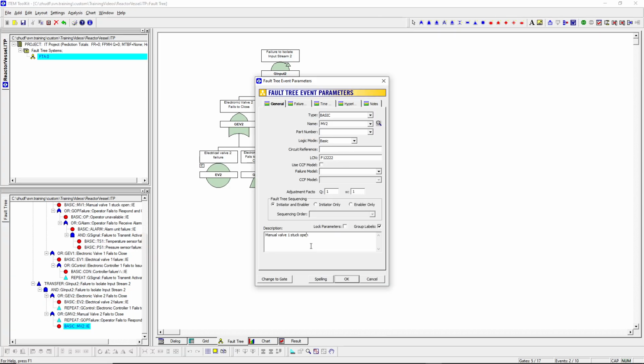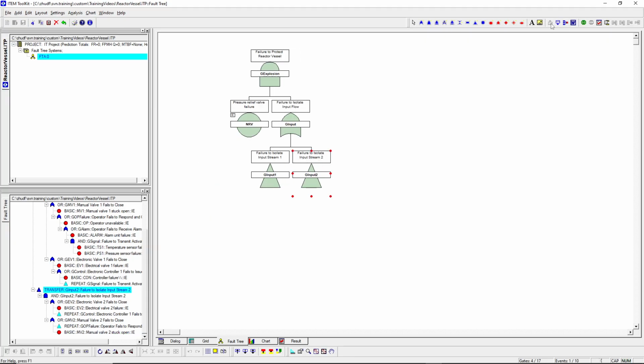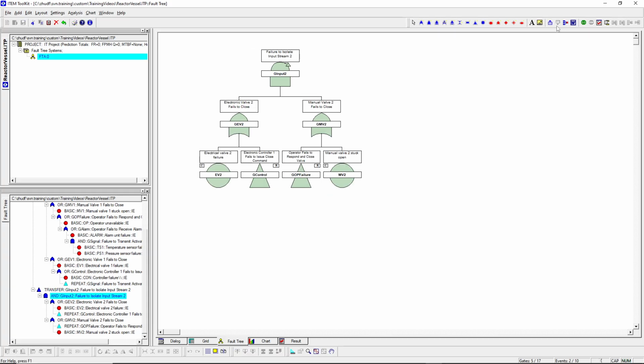That brings us to the completion of our full fault tree structure for the reactor vessel system. In this section, we move from high-level system boundaries down into the granular root causes of failure. By applying the deductive construction rules from Part 4, we systematically broke down our top event, G-explosion, layer by layer. We explored how to evaluate serial and parallel dependencies to choose the correct logical relationships, translating physical system characteristics into and/or gates on our canvas.